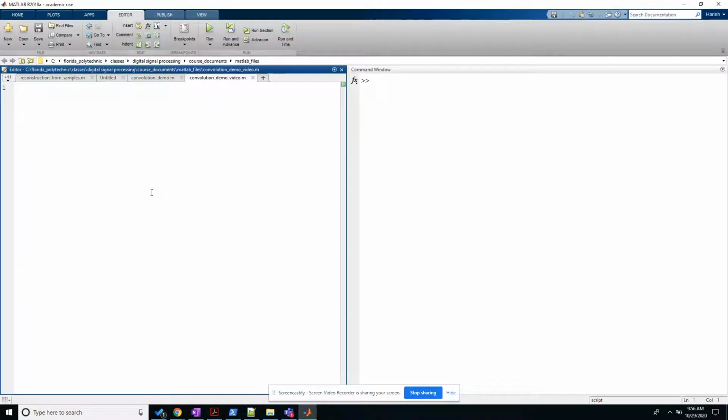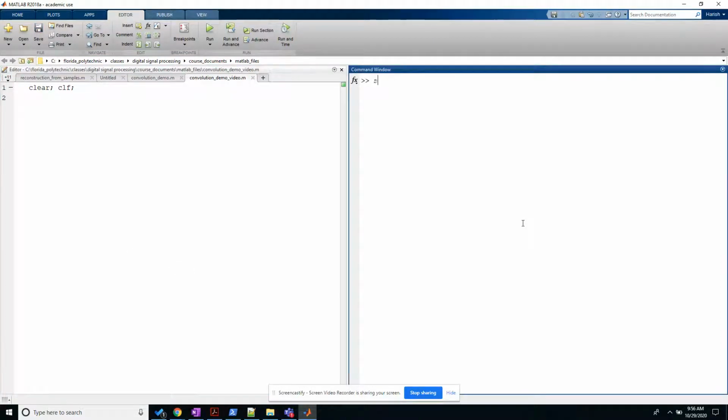So now let's look at implementing this in Matlab. The first thing I want to do is just clear everything so the workspace is clean, and CLF if there's a figure. Okay, and then let's do some initial setup here. So I'm going to do set 0. I like my figures to be docked, so I will just say by default everything should be docked. So figure window style to be docked.